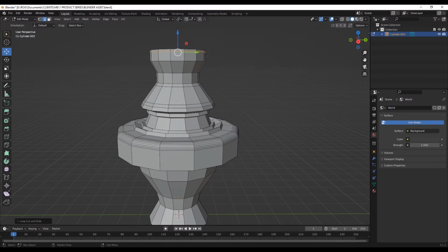So if you want to make cuts manually, you want to slice this object freely, you can go over here to your knife, you place your mouse at your starting position, and then once you left click, you see now that you can move freely. And I'll place this cut here by left clicking, and I'll place another cut here. Then you can just keep cutting as you like. Then once you're done, you can right click and you can hit enter on your keyboard to make the cut.